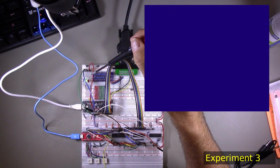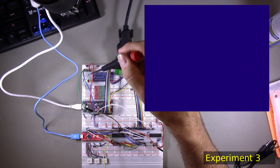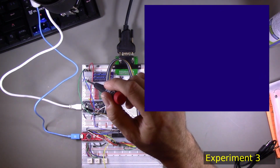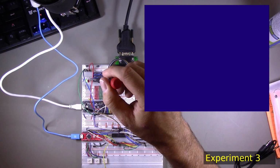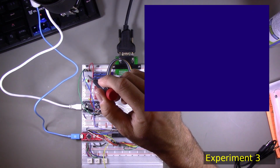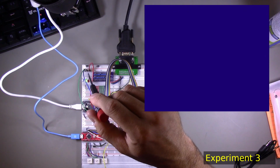What the debug LEDs allowed me to do was, at a coarse level, see what state the command processing state machine was in, and if it went into an invalid state, I would light up the red LED. But the other benefit is I could put oscilloscope probes on the anode of these LEDs, and see traces on the oscilloscope that show me exactly when the debug LEDs are being signaled. That gave me a lot of insight into what was going on at a very tight time scale.